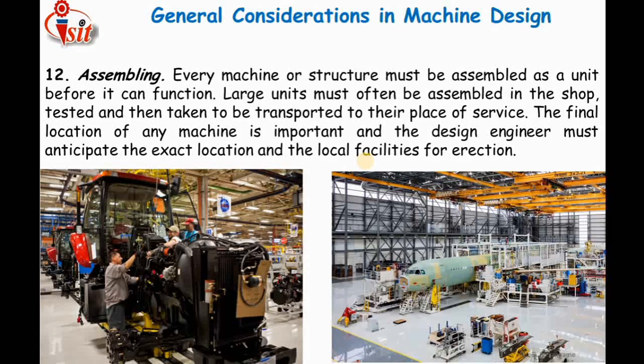I have shown two examples here. One is earth moving equipment, which is quite large. While assembly is possible, and testing is also possible in a few manners, according to the working condition, we might not know for what condition the earth moving equipment, such as a bulldozer, will be used, whether for soft soil or for digging rocks. Creating every working condition and environment is not possible inside the workshop.